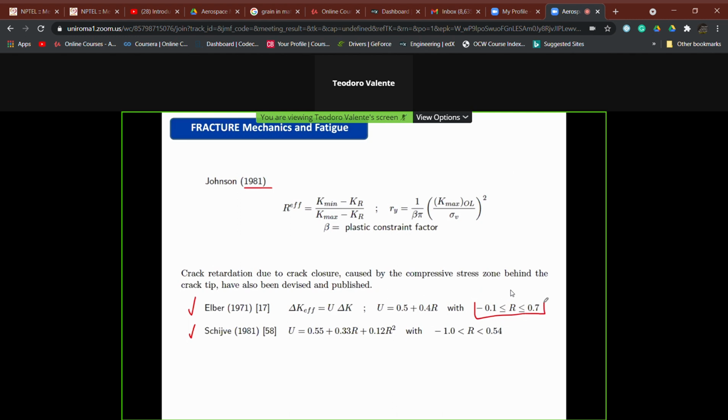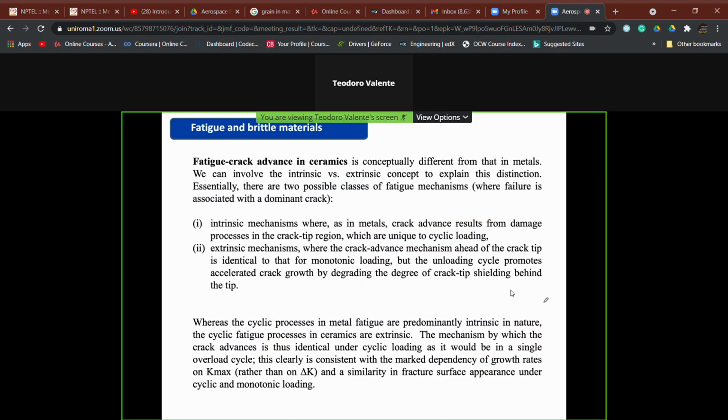This is just to tell you that, at least in the initial phase of crack propagation, the presence of overloads is not so severe, because we can experience a lower crack propagation rate. Thus, for a preliminary design we can neglect this, obviously having assumed that these overloads are not able to put all our material in plastic deformation, and we are authorized to use the most simple models, even though some experience and modeling have been made also in this case.